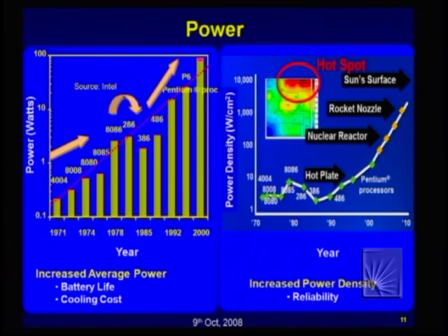It turns out that the power density across the die is not uniform. The region which has the higher activity will have the high power density. So, if you are trying to design a circuit to reduce the power density, you have to actually give more emphasis on this region, which is typically the integer arithmetic logic unit and integer register file, which has the highest activity, because the power is proportional to activity and temperature or heat is proportional to power.